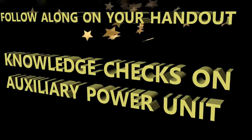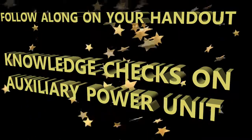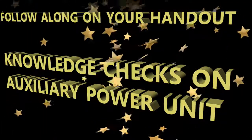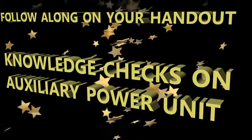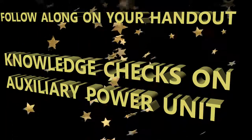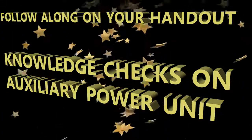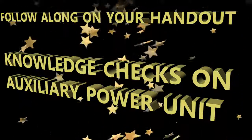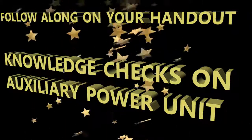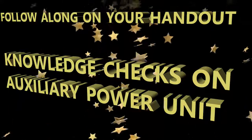Oh yeah, and access on the doors. The doors themselves, I do want to cover that. You have a left and a right access door, okay? And in order to access the APU, the left door needs to be opened first. So keep that in mind. Okay, that's number 16 on your sheet. The left door needs to be open first before the right one, in order for you to open the door so you can get access to the APU.